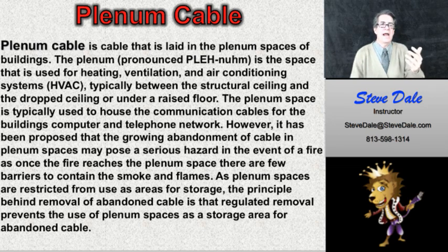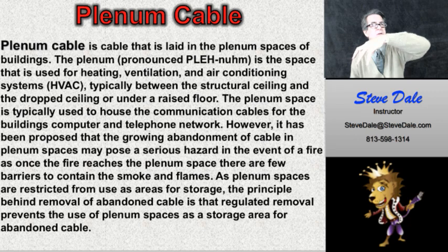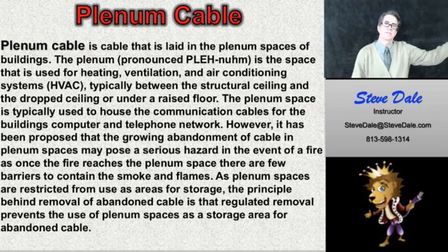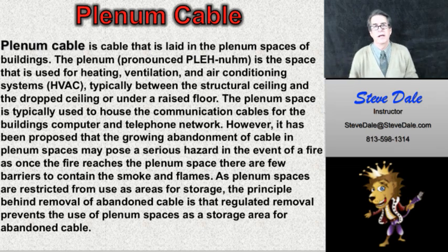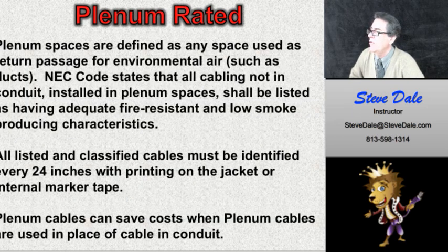Because what you don't want to have happen is you get a fire up there in those drop ceilings, or in an area, and guess what happens? All that smoke is drawn into the heating and ventilating system, right? The HVAC system, and it's pumped out through the rest of the building. And of course, what's that going to do? You know, smoke is what kills people, even most of the time before the fire does. So you have to know about plenum spaces. You have to know that in plenum spaces you need to use plenum rated cable, or the cable needs to be in conduit. Okay.